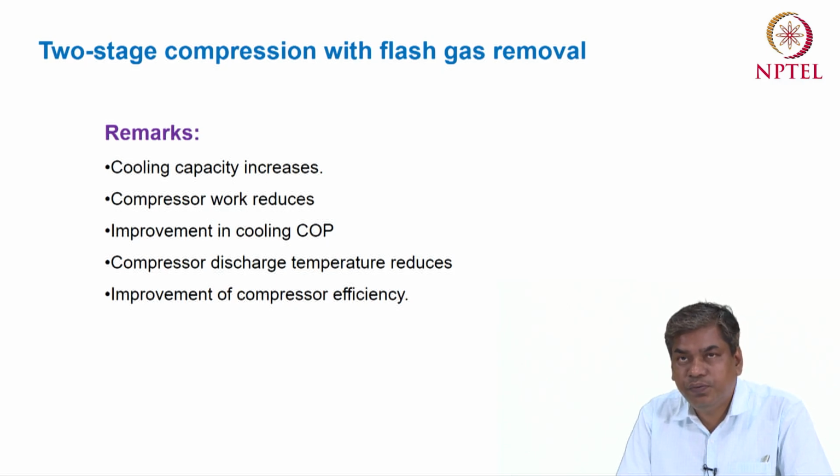So with this modification, the two stage compression with flash gas removal, the cooling capacity will increase, compressor work will reduce, the COP will increase, and the compressor discharge temperature will reduce.